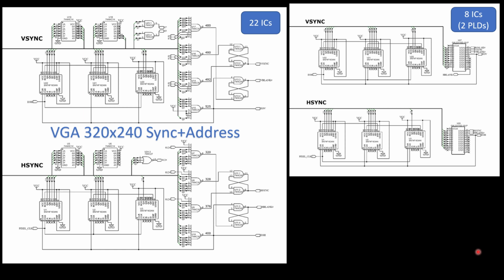The software that I use, it's called Digital, lets me just easily lay out the logic with gates, drag and drop and connect the wires. Or I can even import an Excel spreadsheet that has all my logic, essentially a truth table of what I want to see for output, and it'll generate all the appropriate gates for you. All that can be done in Digital. It's really easy, and so that then lets me program these PLDs.